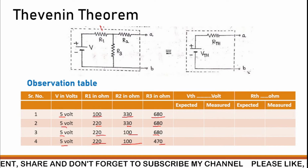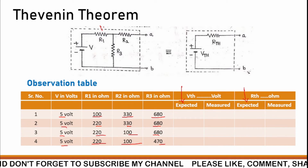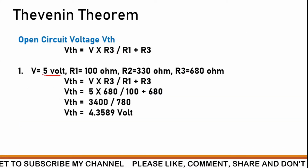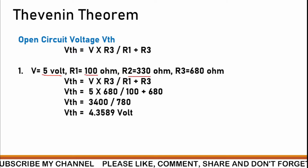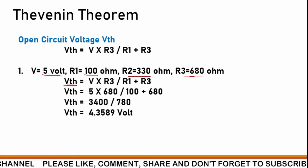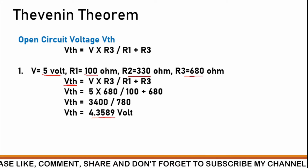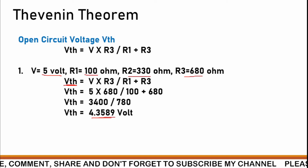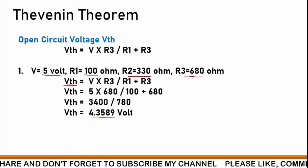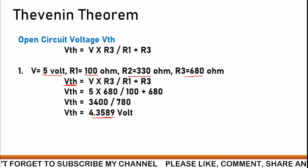So what we are going to do is calculate the expected VTH first, then the expected RTH. You can look here: when V is 5 volt, R1 is 100, R2 is 330 and R3 is 680, by putting these in the formula of VTH, we get 4.3589 volt. You can pause the video, write down all these readings in your notebook, and complete the observation table, and only then will you understand how these values come from the formula.